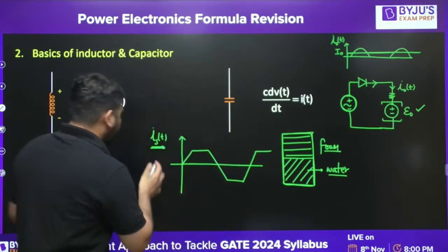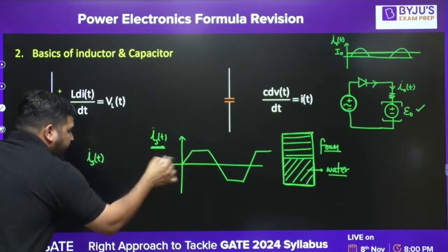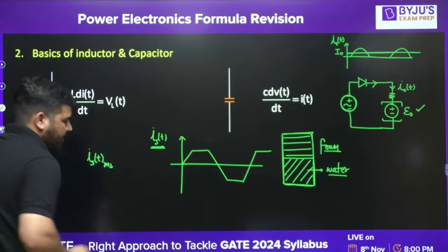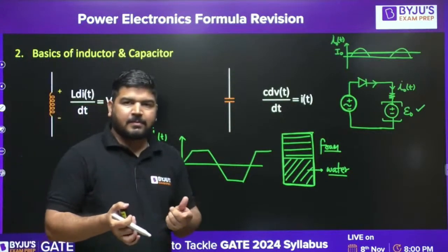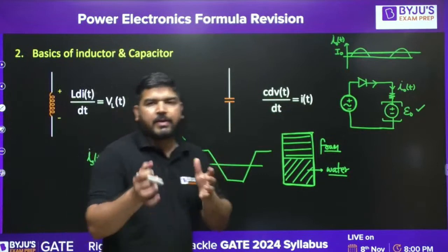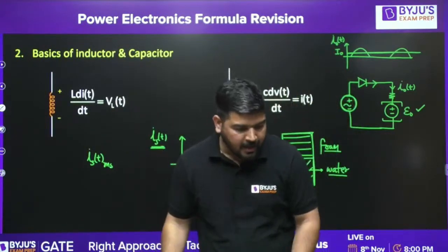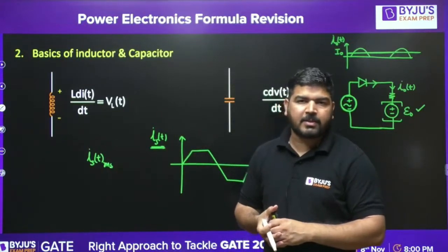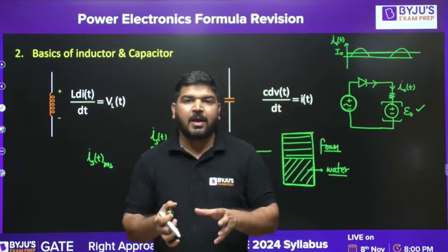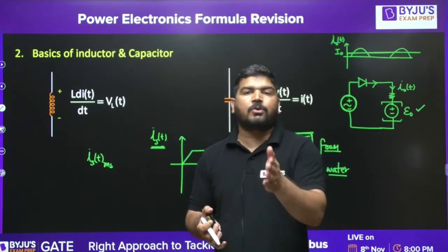So what I can do is find the RMS value of this entire signal. In this RMS value, there is a participation of every frequency term, fundamental and higher frequency terms. Now, I want to find the RMS participation only because of harmonics.